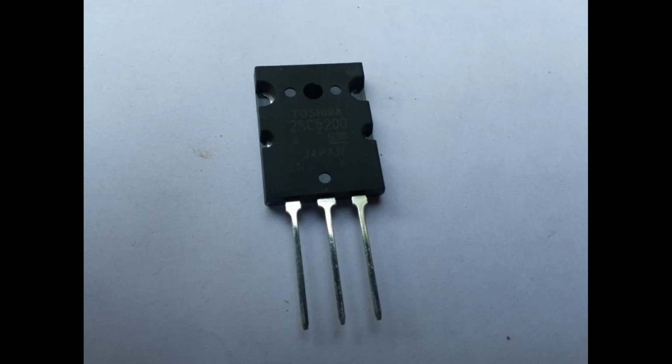Linear voltage regulators use a transistor, usually a bipolar junction transistor, to regulate the output voltage. Here's how they work. Input and output: the input voltage, usually unregulated, is connected to the regulator's input terminal, and the load, the electronic device that requires a stable voltage, is connected to the regulator's output terminal. Transistor control: the transistor acts as a variable resistor, adjusting its resistance based on the difference between the desired output voltage and the actual output voltage.